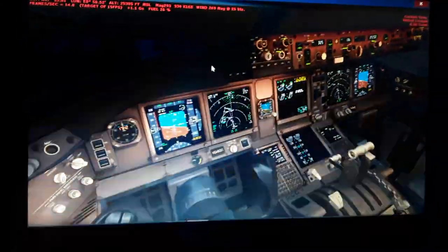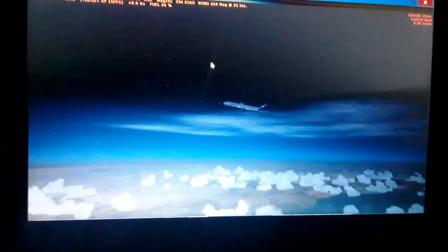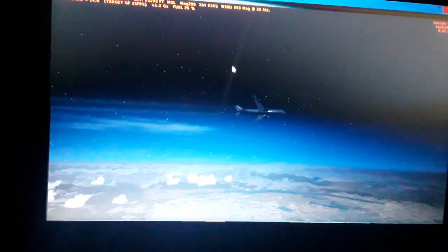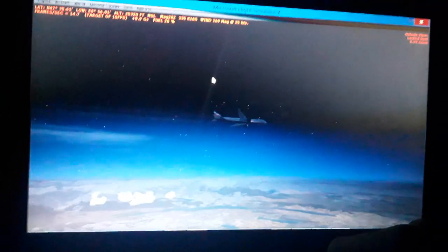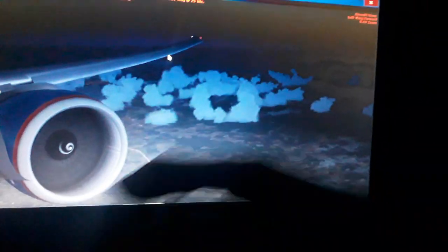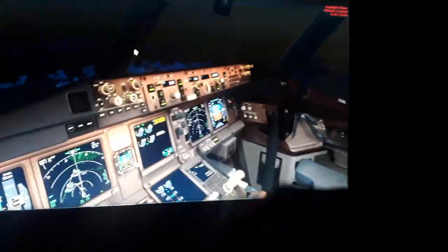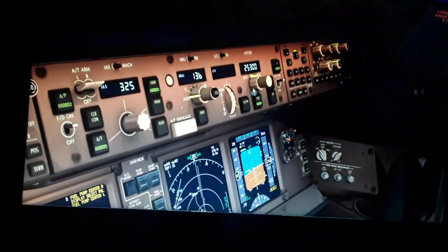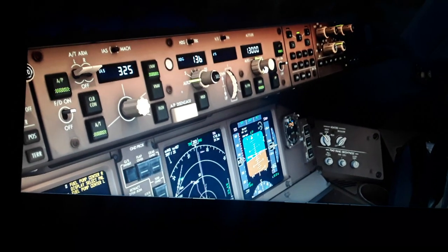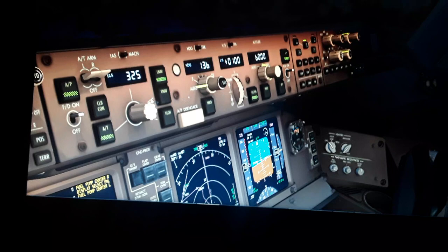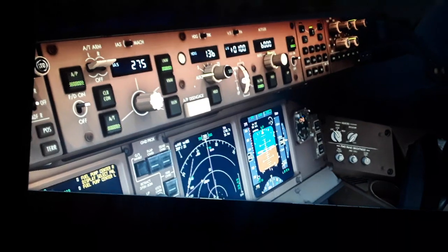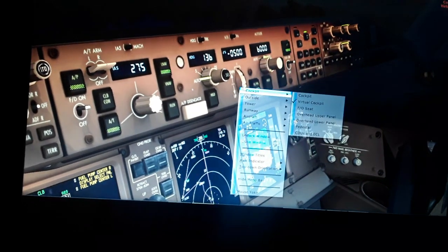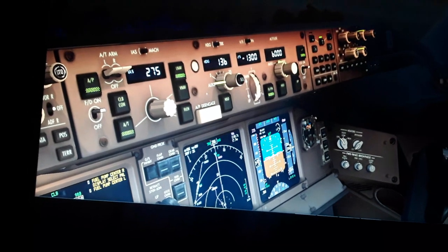Also this beautiful view again from outside, and we have 8 minutes left. We have again no frozen vapors, 980 kilometers in cruise with the autopilot, and we're gonna start now descending on the aircraft. So we're gonna select a lower altitude now, and decrease the airspeed a little bit, and we're gonna increase the rate of descent.